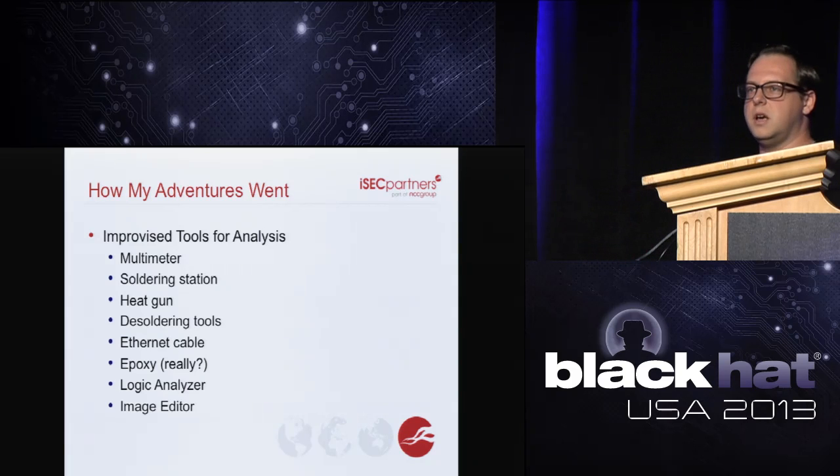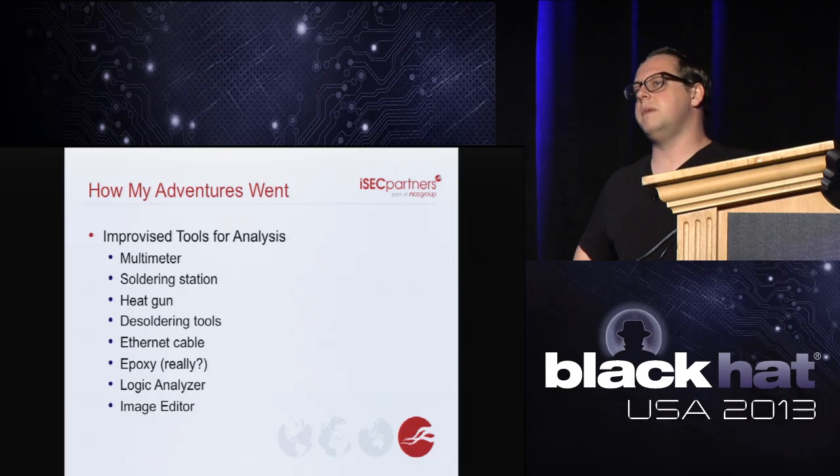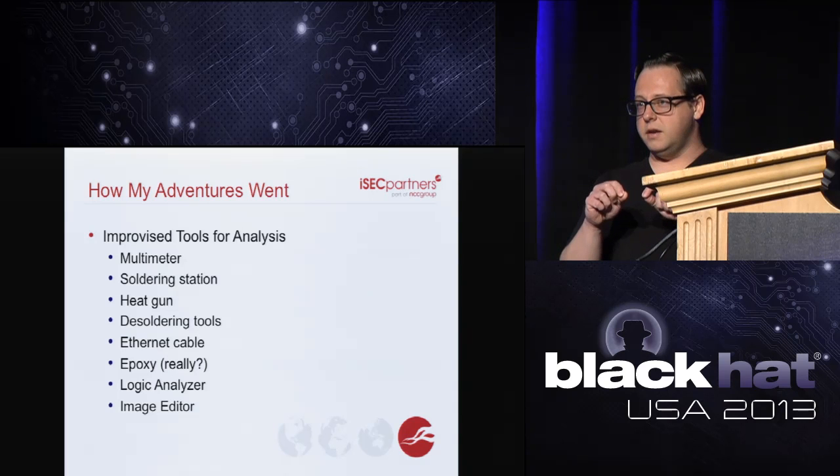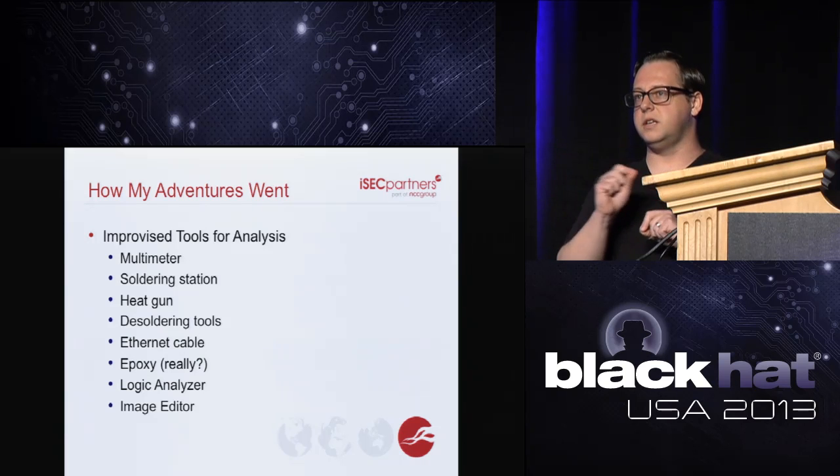Some of the tools that I used: a multimeter. A multimeter is amazing, especially for the continuity testing feature. We're able to touch different wires together and different traces and different vias and trace where signal is flowing.